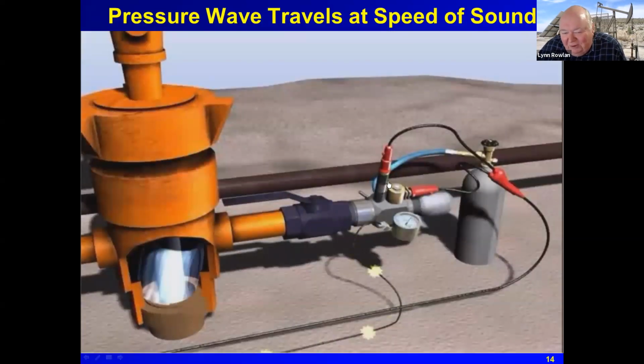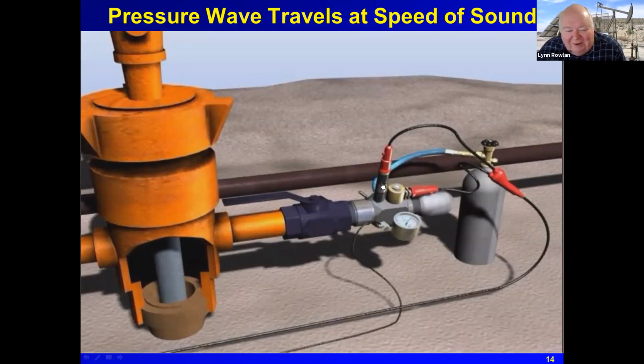And also we have this pressure gauge here that's measuring pressure at the surface. And then we measure pressure over a period of time, maybe just 2 minutes or maybe longer. And since this valve on the other side is closed, the gas that flows by the pump makes this pressure at the surface of the well go up. And we read the pressure, and the change in pressure versus time represents the gas flow rate in the casing. And it also represents the bubbles that bubble through the liquid above the pump.